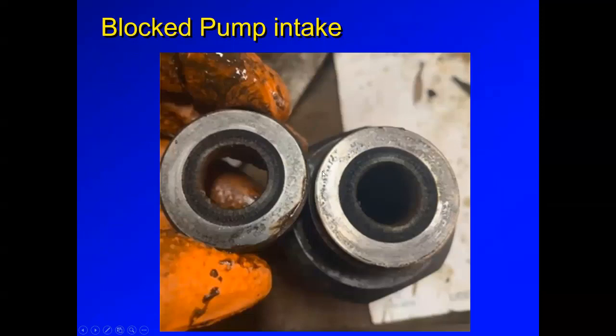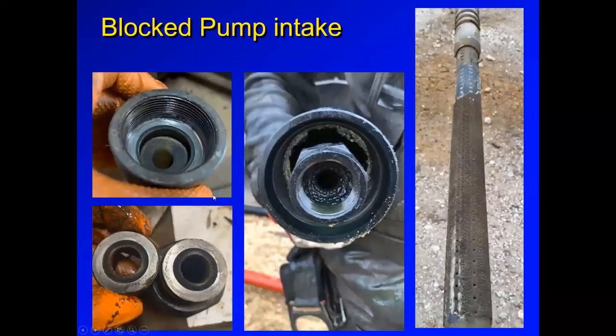Examples of pump restrictions. If you see some buildup, and there's a lot of scale in these wells, sulfur, iron, anything that's blocking the flow, you see how severely choked this pump is. These were good pictures from Justin.